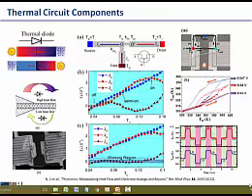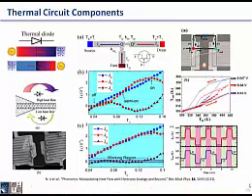It is a vanadium dioxide nanowire sitting between two heat sources, which control two temperatures. This material is a phase transition material that, when you change the temperature, goes from an insulating state to a conducting state. It also has a hysteresis loop. So people are using temperature to switch it between two different states to realize this memory operation.